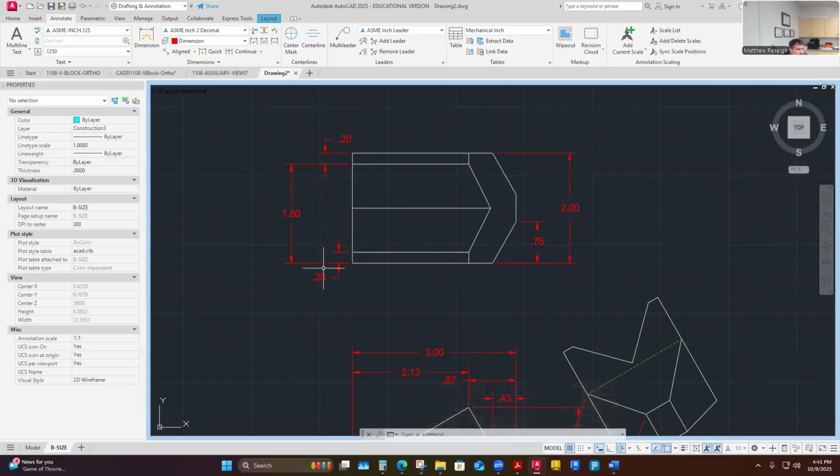I feel like I've got more controls happening from the front side surface and up and to the back. So this is kind of an oddball. I would think that one of these is going to become, I don't know, I just have to determine that maybe one's going to become a reference dimension. And then I may dimension it differently once I know that. But right now I'll just leave it. It's not a redundant dimension. It's a separate feature than this.